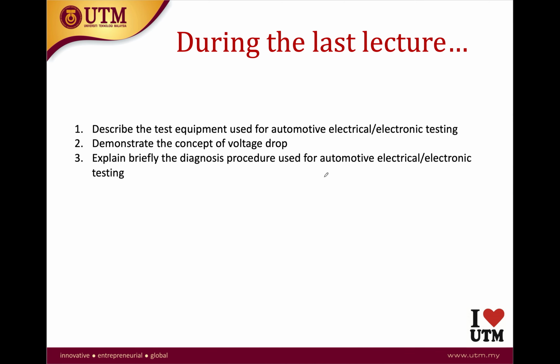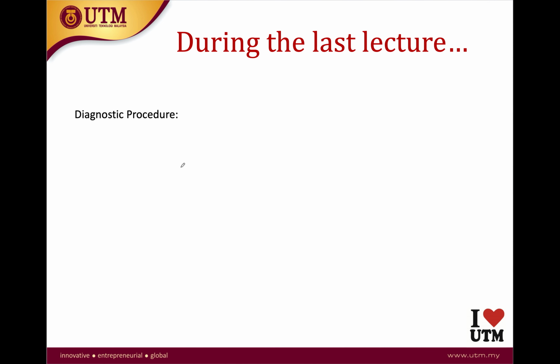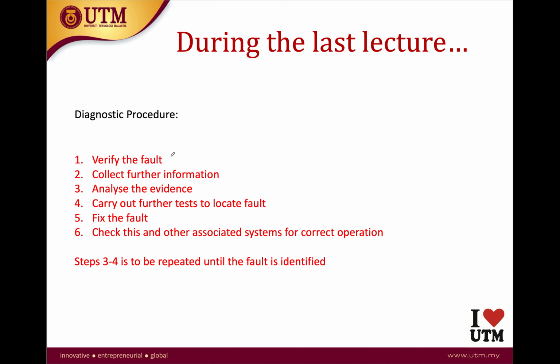In the previous lecture, we looked at the types of test components that can be used for automotive electrical and electronic testing, and we defined voltage drop. So what is voltage drop? We also discussed the steps used to systematically diagnose a problem or find a fault in an automotive electrical electronic system. The diagnostic procedure includes first verifying the fault, collecting further information, analyzing the evidence, and carrying out further tests to locate the fault.